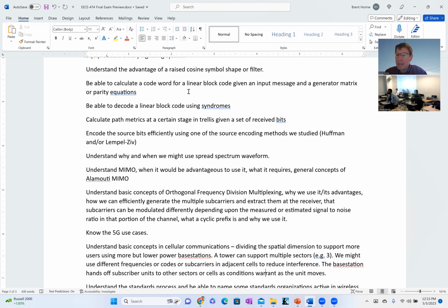Then for a systematic code, we know that the first few bits, in the case of 4 input bits, those first 4 input bits would be directly from your code word, right? So if your code word is 7 bits long, and your generator matrix starts with the identity matrix and then follows with the parity bits, which is just by convention how we've taught it.